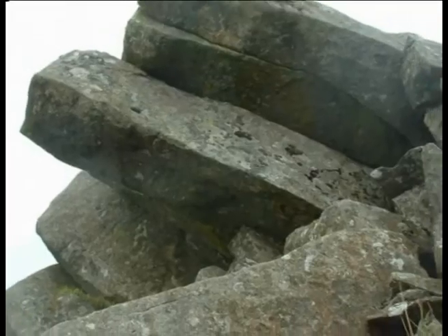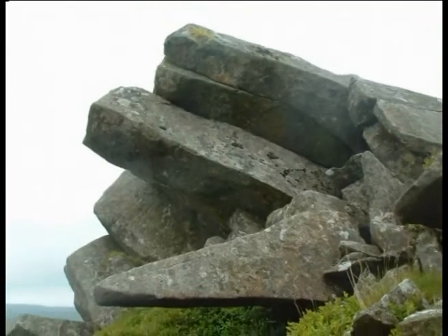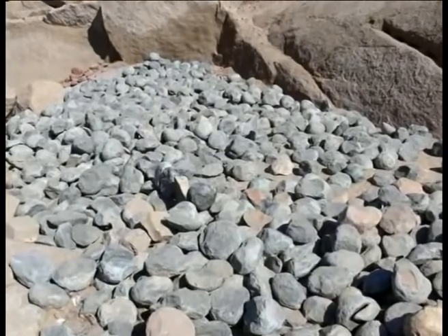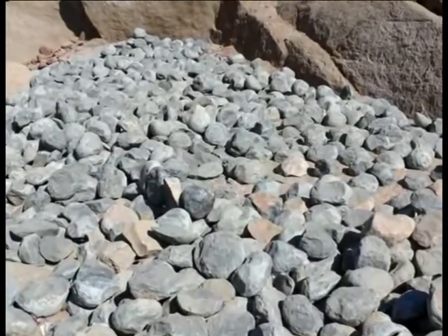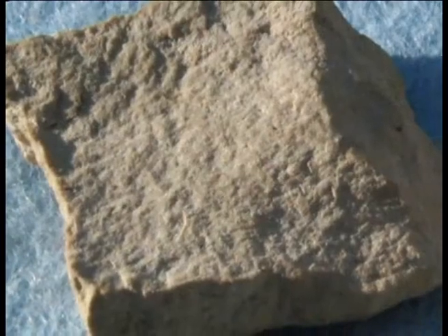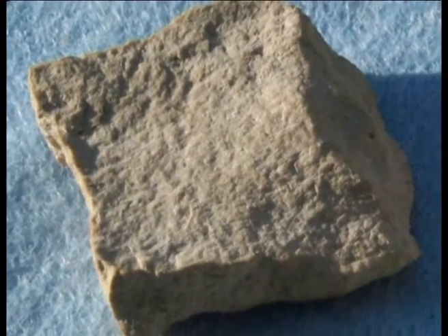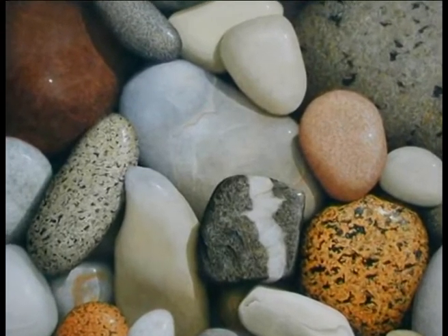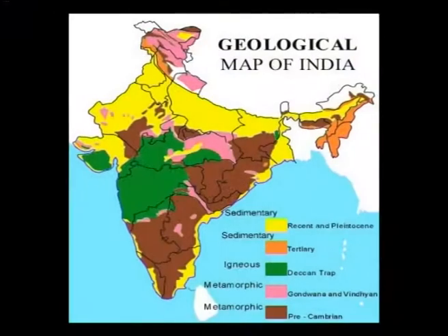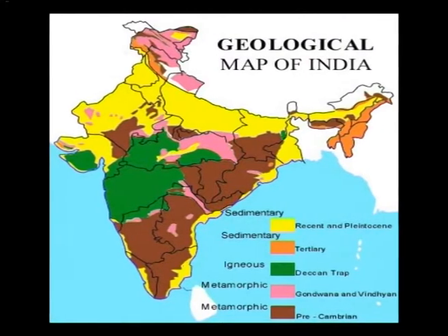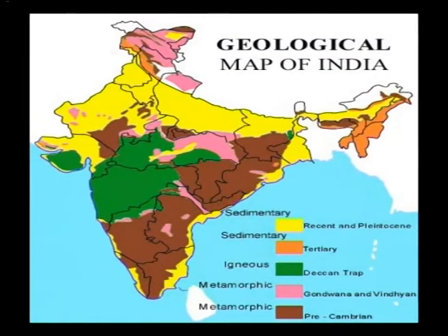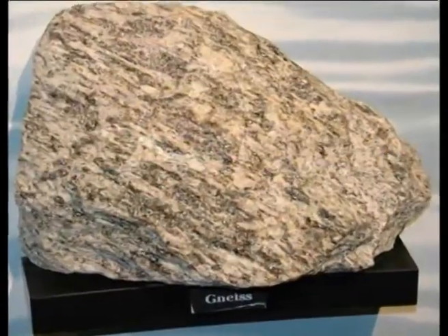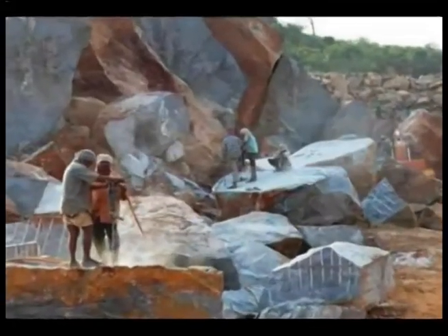Granites. These are the most commonly used building stones of all the igneous rocks. They generally possess all the essential qualities of a good building stone, showing a very high crushing strength, low absorption values, least porosity, interlocking texture, variety of appealing colors and susceptibility to perfect polish. India has got good reserves of granitic rocks. The Archean group of rocks of peninsular India are comprised chiefly of gneisses and granites.